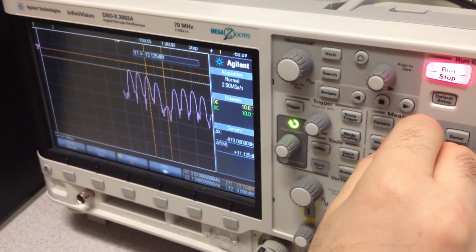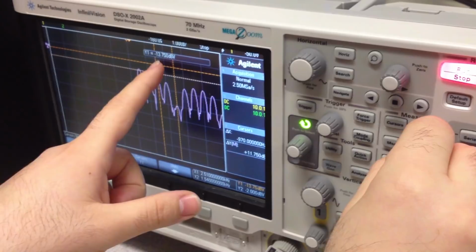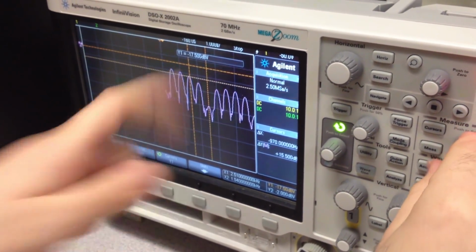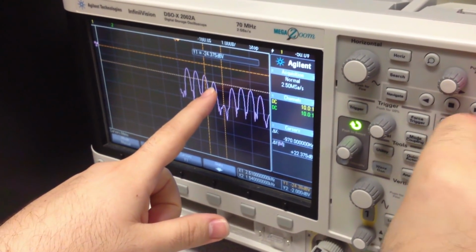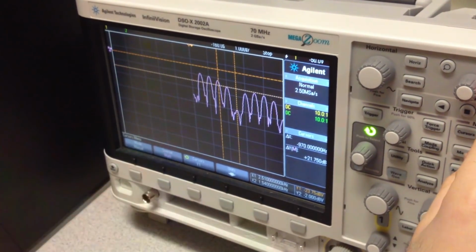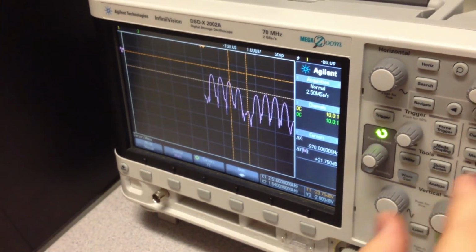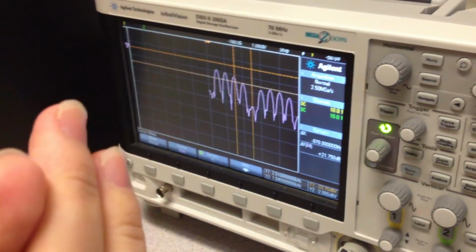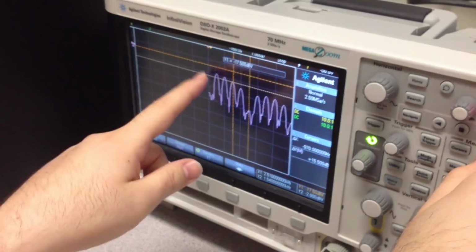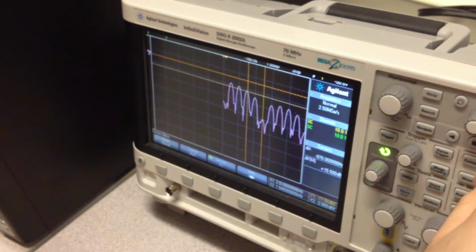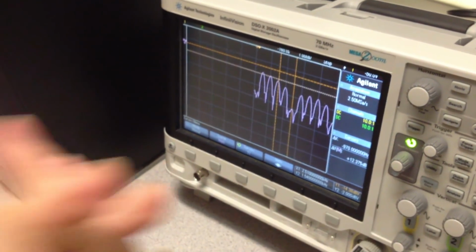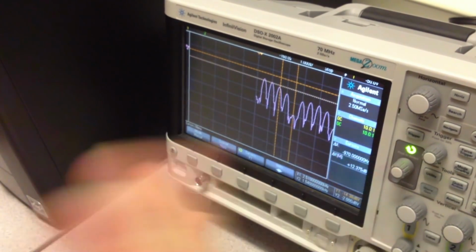The second bin, negative 13.75 dB. Write it down. Here, negative 17.5. Write it down. Negative 23.75. Try to be as accurate as you can. But as I told you, it will not be 100% accurate. So I try to write down the values of maybe the first 4 bins, which is okay, to make sure that these bins are correct relative to the theoretical ones.